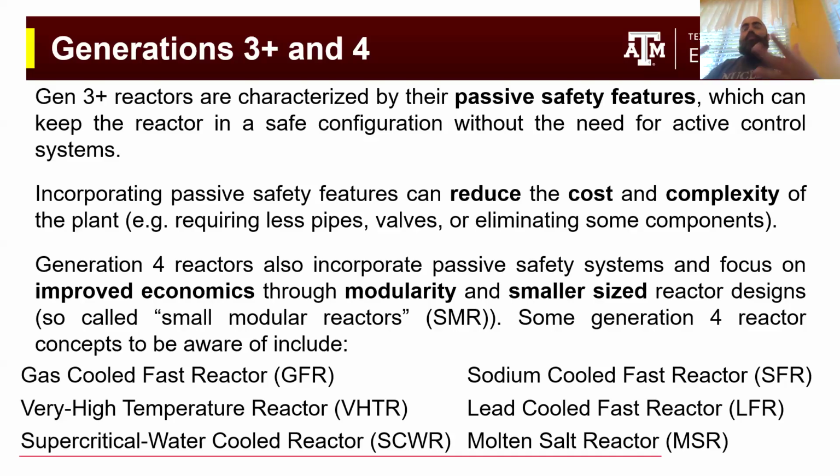So you can engineer your facilities, and also some parts of your reactor pressure vessel, such that it gets a natural circulation flow just because of the physics of buoyancy and the geometry and where the temperature gradients of your system are. Those passive safety features can protect the reactor during an accident, and it doesn't require on-site power. It doesn't require a pump to be able to use natural circulation.